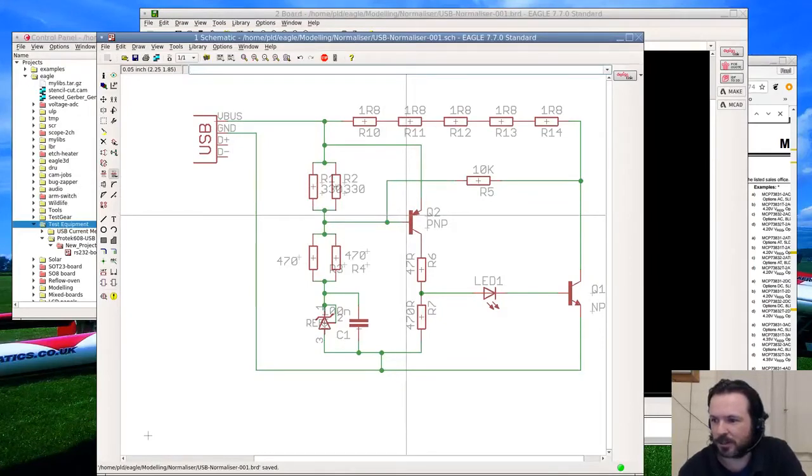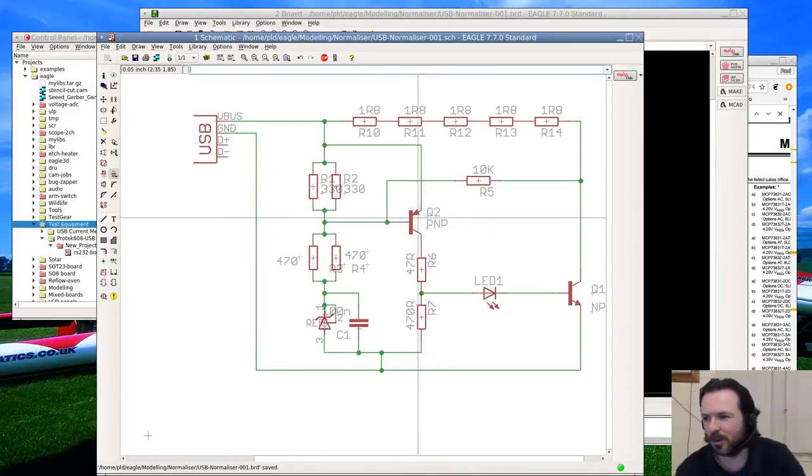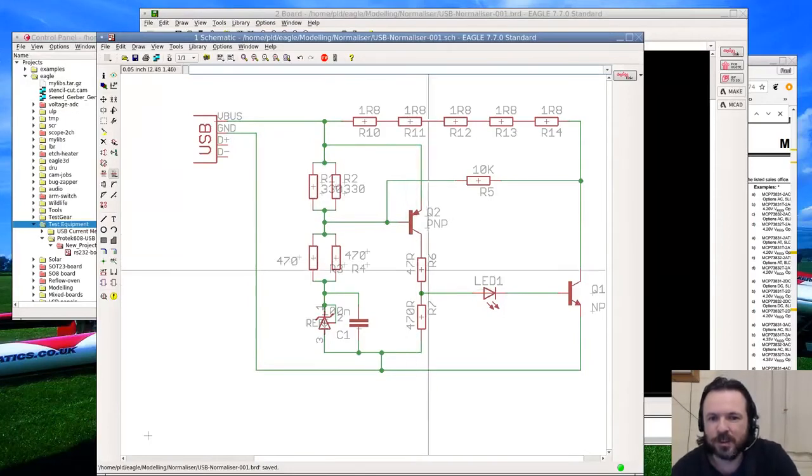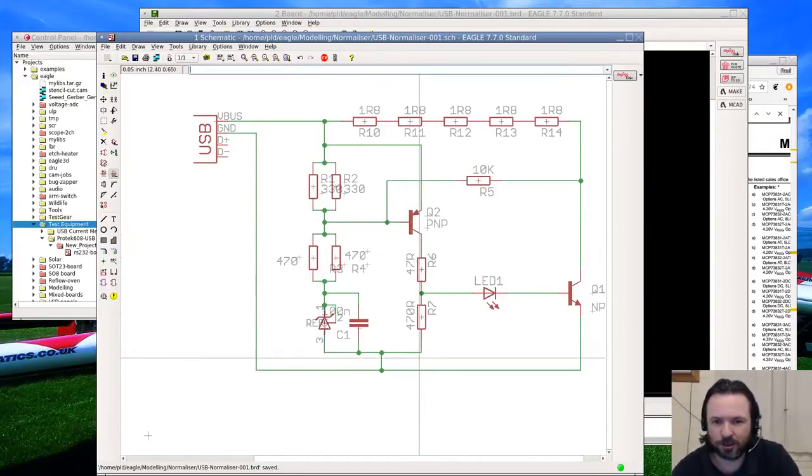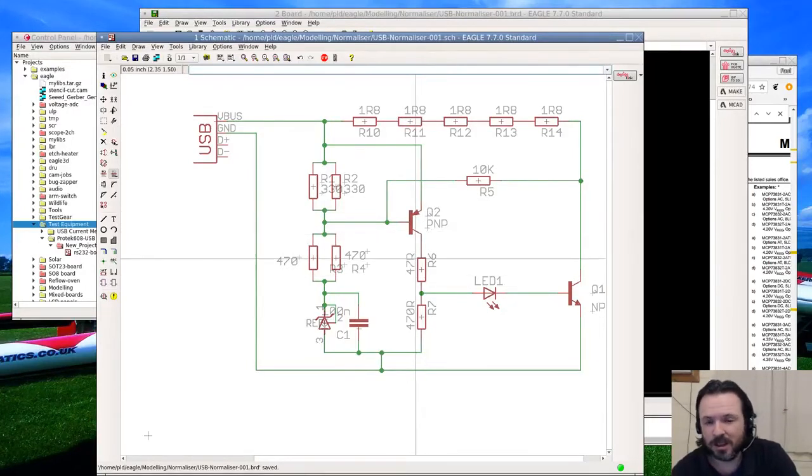Anyway, so what happens here is there's enough of a voltage drop across this top section to push this gate open. G'day Spencer. And when this gate gets pushed open, you'll see about a 0.6 volt drop across it. I shouldn't really say pushed open, it's more like the collector and the emitter get squeezed together down to 0.6, so that's what really happens. And the current will flow through here, and then we'll have enough of voltage across here. It will be like 4.2 minus 0.6, so that's at 3... brain fade, 3.6, something like that.